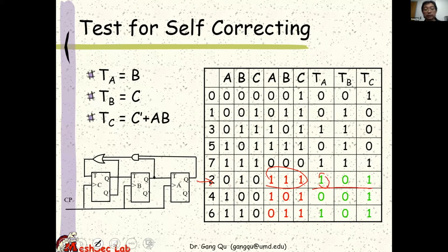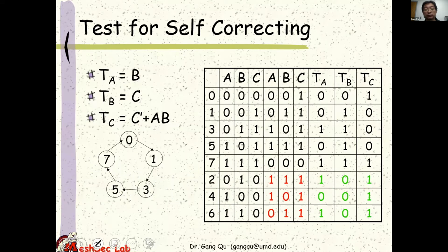Now let's come back to the finite state machine level. This is the initial state machine we're supposed to implement. After I've done this circuit analysis, I know for the other 3 states that are not specified here what their next state will be. So I add this to the final state machine, and now I have a complete state machine with all 8 states.